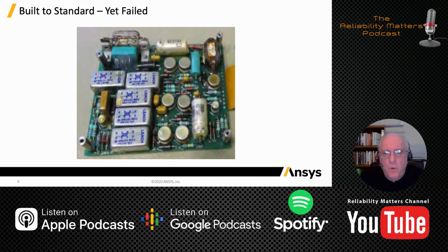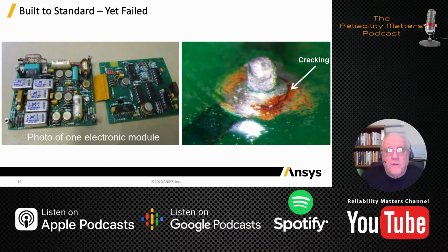And yet the board is only supported on the four corners. You can see the standoffs there. This circuit board and the rest of the boards and designs of that particular module all met the standards. And yet, like the deck that I talked about earlier, it didn't take into account the long-term effects of vibration, and the solder joint cracked and failed.